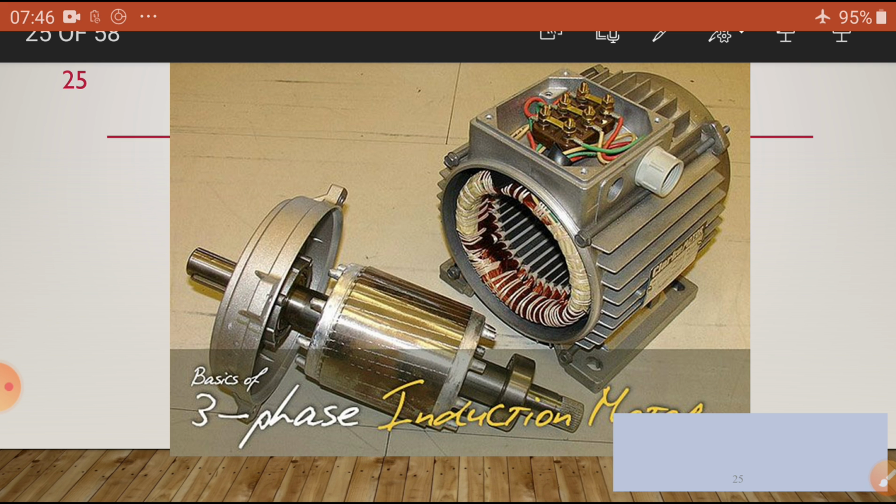Now, in this case, the voltage given is 20 to 30% of rated voltage only, such that you have to see the rated current flowing in the ammeter. So, in the blocked rotor test, you have to give the rated current to the motor. In the no load test, you have to give the rated voltage to the motor.